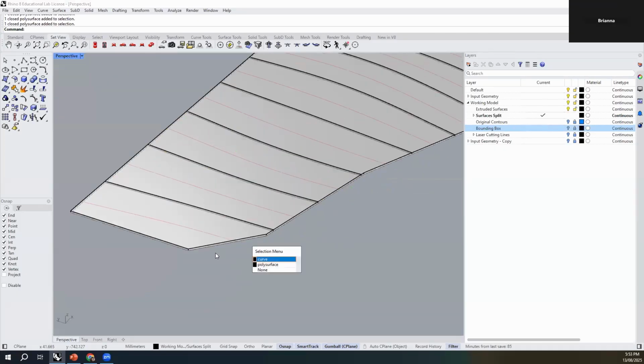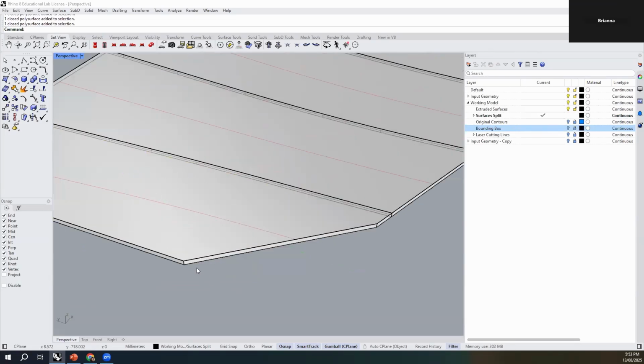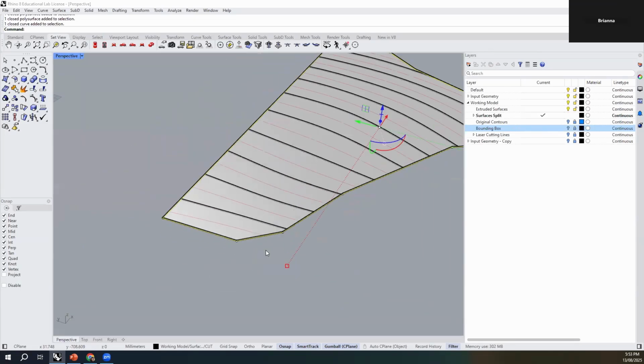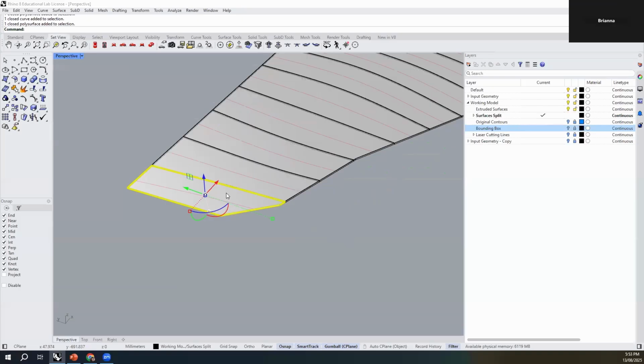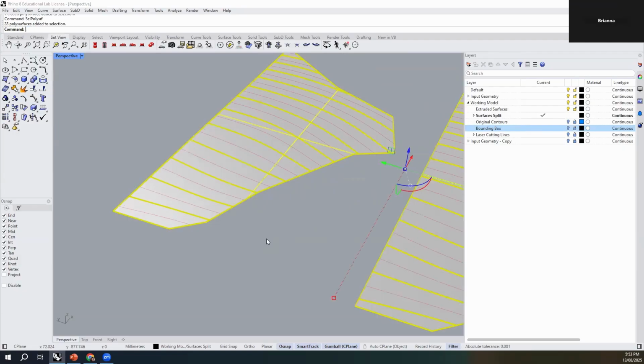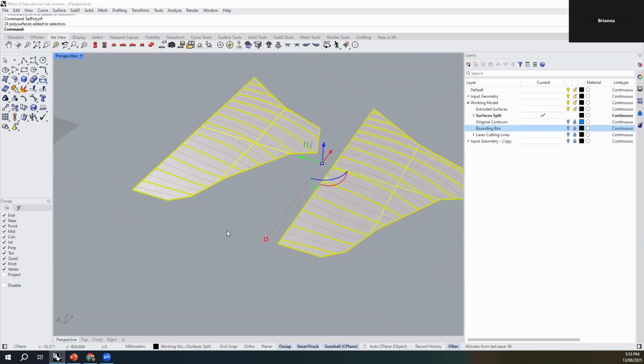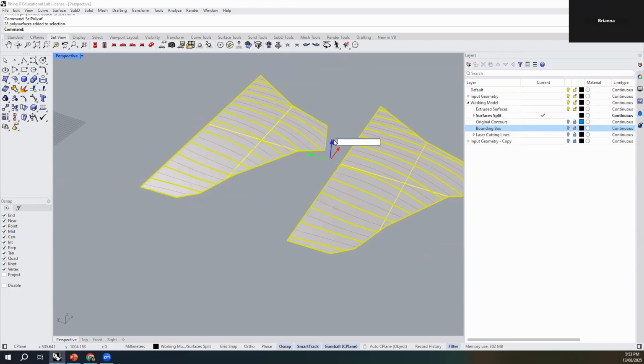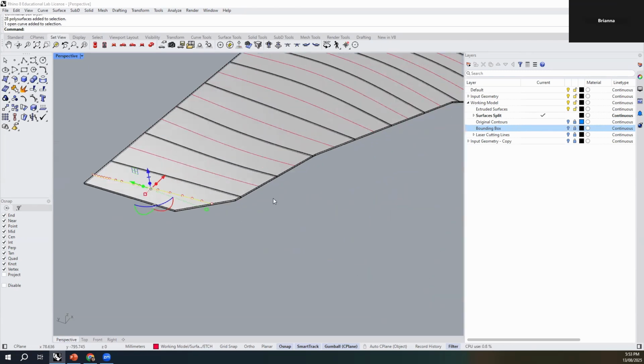These are poly surfaces, so they are blocks. We still have all our other geometry. It actually hasn't gone into the negative space, which is a little bit annoying. So I'm going to use sel polysurf, so select the poly surfaces, and I'm just going to use my gumball quickly. Click on that arrow and say negative 1.8. Great. I can see that my etch curves are right on the top surface.